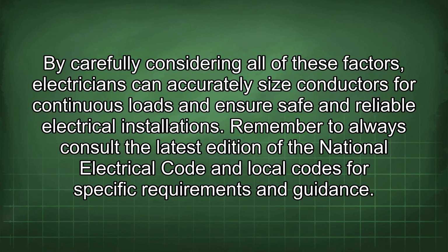By carefully considering all of these factors, electricians can accurately size conductors for continuous loads and ensure safe and reliable electrical installations. Remember to always consult the latest edition of the National Electrical Code and local codes for specific requirements and guidance.